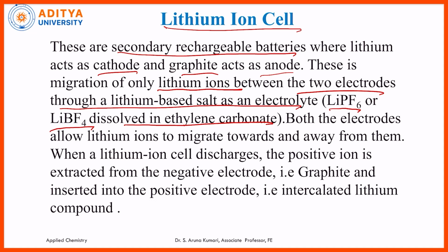The reason we have not selected any water soluble electrolyte is that lithium is highly reactive with water. So, we have to remember that in lithium ion cells we have not selected an electrolyte like sodium hydroxide or potassium hydroxide. Instead, we have selected a salt like lithium hexafluorophosphate or lithium tetrafluoroborate dissolved in ethylene carbonate.